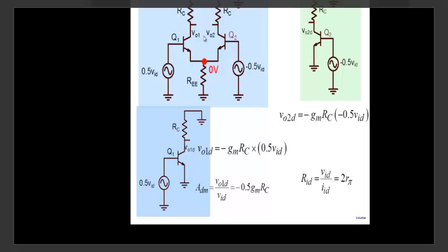Now, one point that I would like to emphasize is this is a perfectly symmetrical circuit. Perfectly symmetrical, transistors are the same, RCs are the same, and obviously you can see that I can put ground. So in this case, it's obviously valid. But there can be situations here, let's say when I have RC1 here and RC2 here. Say 2K here and 4K here, or whatever. The resistors are not the same. Now, you may think, can I make it ground? The answer is strictly no, but practically yes. Okay? Strictly speaking, it is no longer fully symmetrical, and therefore this will not be valid.